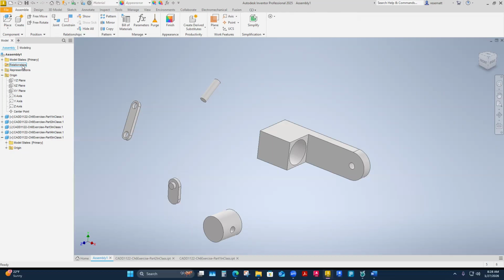You have to kind of keep track, because you're going to apply constraints, and sometimes you have to manage and move parts and undo constraints. This was really frustrating for me to learn, just how to apply constraints and what the best constraints to apply are. It's the same as building a part: at first it's going to be sloppy, and then you're going to get better through practice and time and having to undo constraints. Frustrations like "oh my gosh, it doesn't move the way I want it to" will help you iron this out.